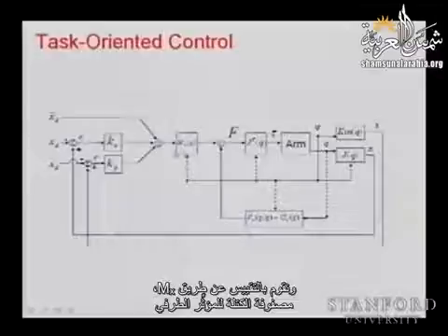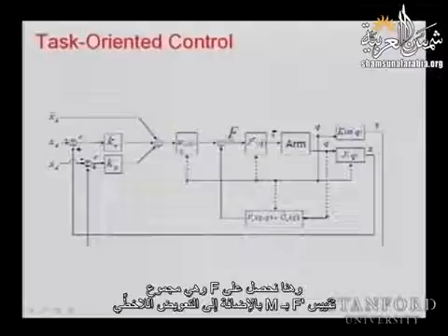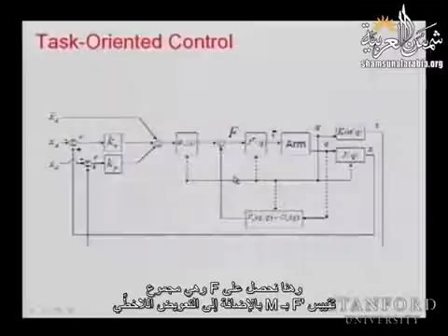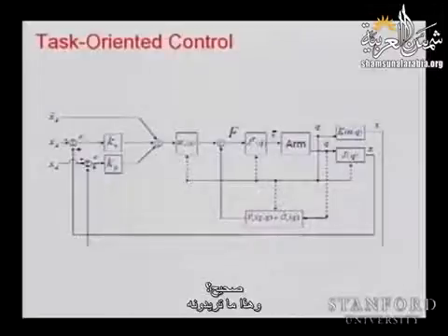And we are scaling with an MX, with the mass matrix of the end effector. And we are controlling the trajectory. So here we control an F prime. Here we get F, which is the sum of scaling F prime by M and adding the nonlinear compensation. And your dynamics now is controlled in task space. Right? And that's what you want.